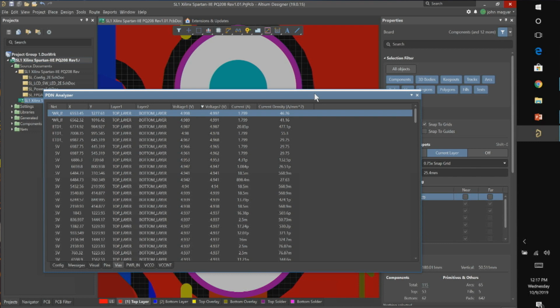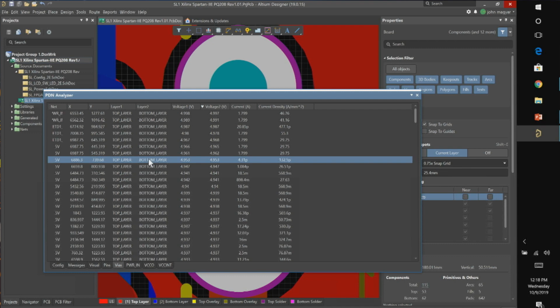And another thing is, we're not in all cases taking into account the enclosure. So you get airflow and things like that. So we're really not set up for that type of analysis. That's something you could do probably in any number of analysis tools, such as SolidWorks. I think they have a thermal analysis capability, and that would take into account the full enclosure and other environmental factors. So what we're looking at is a way to make sure that all conductivity from a source to each pin of the load is adequate, and you can set checks similar to design rule checks to flag things that would be of great concern.